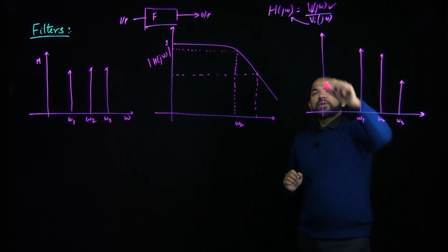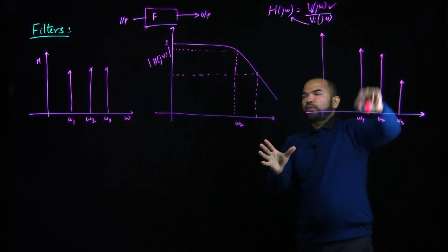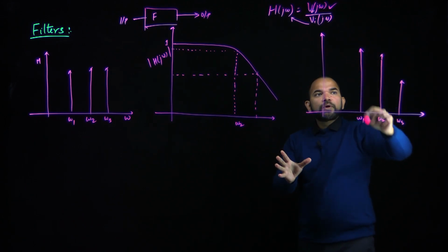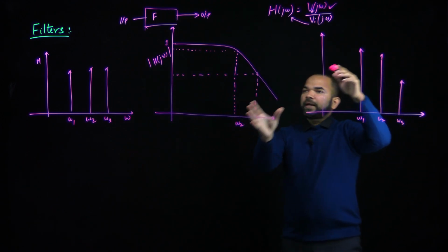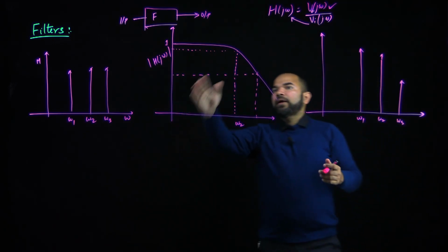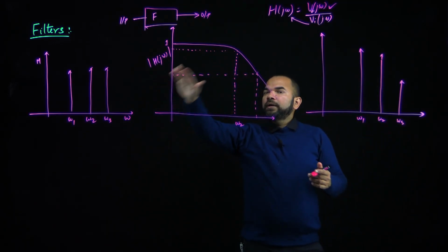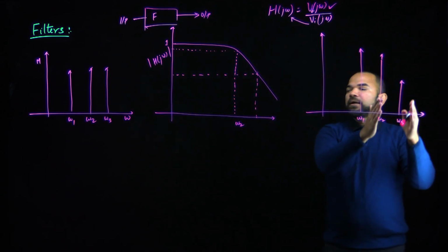So what we are doing here as a filter response is that we are not affecting certain frequency components. There could be one limit where we can say this filter response is starting its stop band, and then we see how the transfer function is falling off in the stop band and how other frequency components get attenuated.